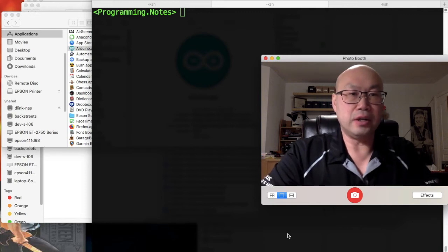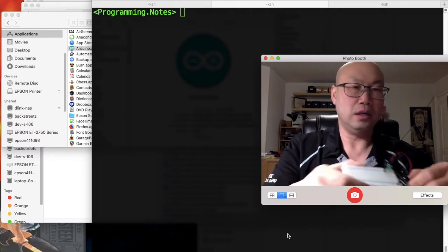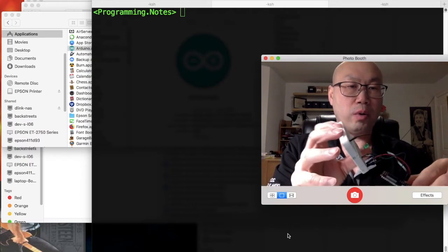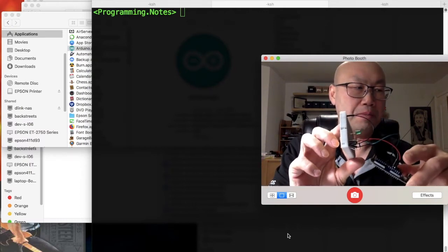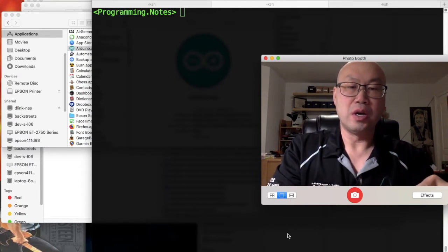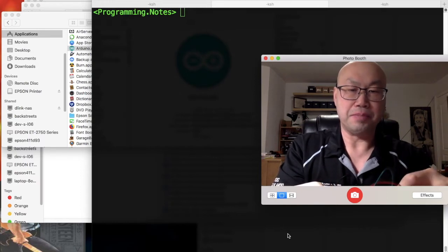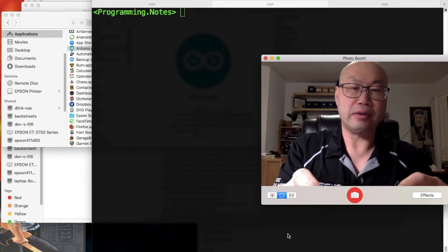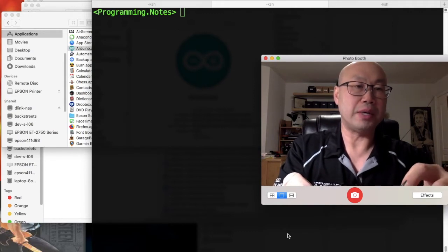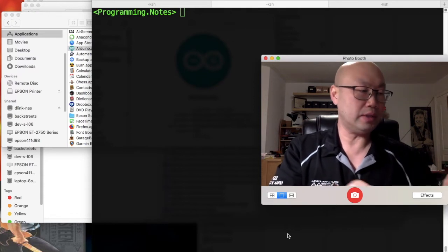In our last video, I showed you how to connect an LED to the breadboard and then wire it to the Arduino. And now we're ready to program it. Just as a refresher, we've connected the green LED, and from the positive end of the green LED, this green jumper cable is hooked up to pin number 8. That's going to be really important to remember as we do this.